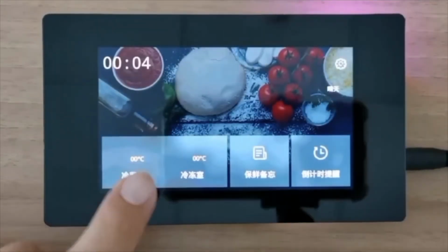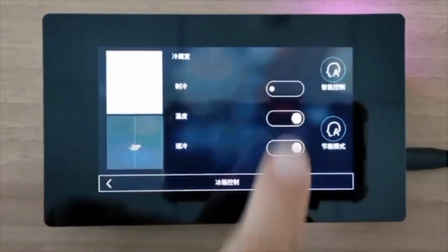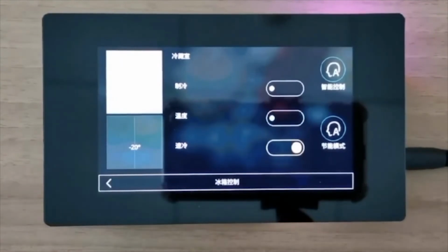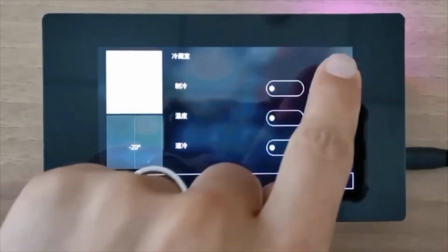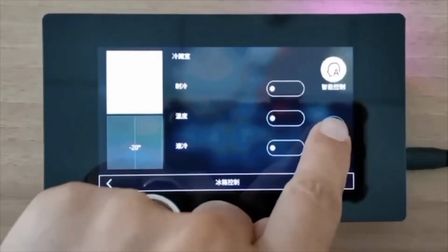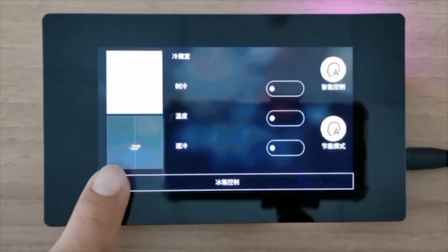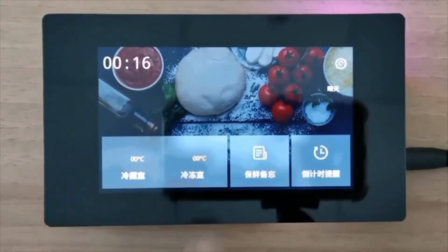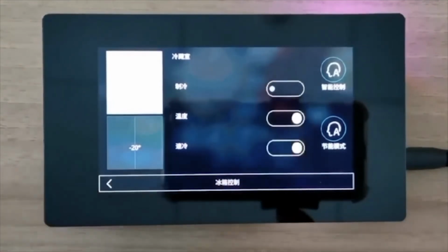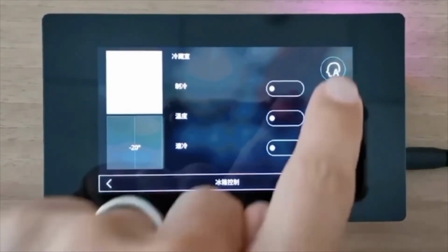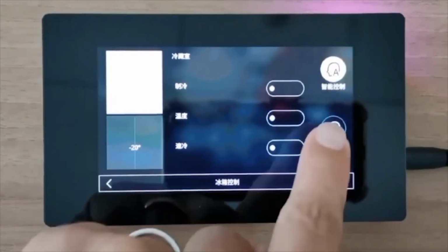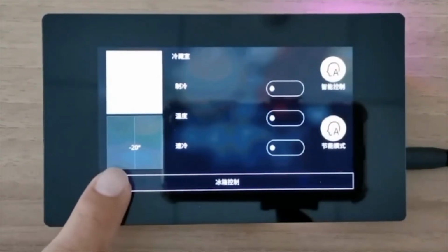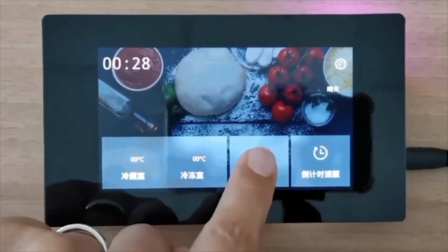Today we are looking at a Mixel customer demo from Hercules Microelectronics. This is a human-machine interface, or HMI, solution based on the HME H1D03 FPGA, which can be used for smart home appliances such as refrigerator, ventilator, and air conditioning control panels. In this demo, we see the GUI for refrigerator control. The H1D03 supports MIPI, LVDS, and RGB display interfaces up to 1080p.